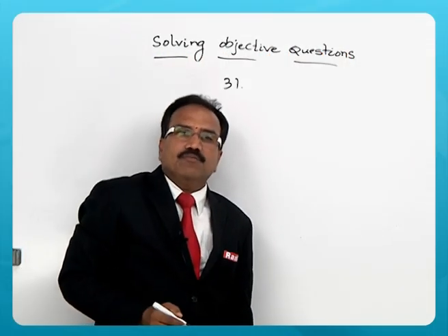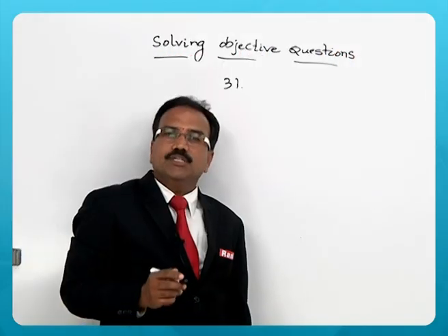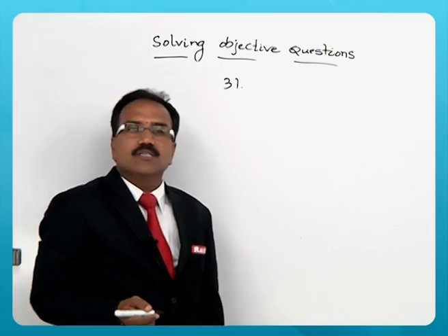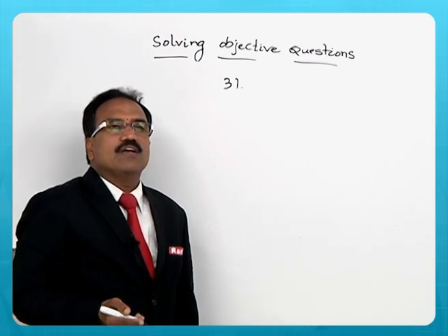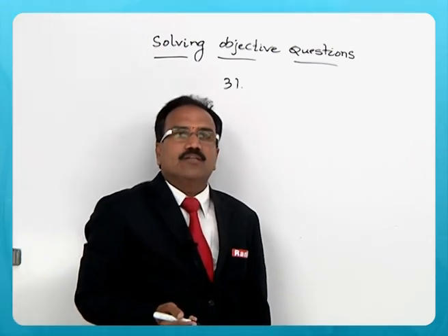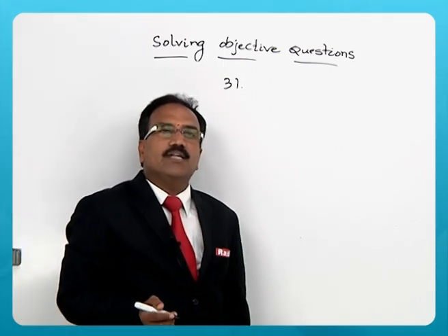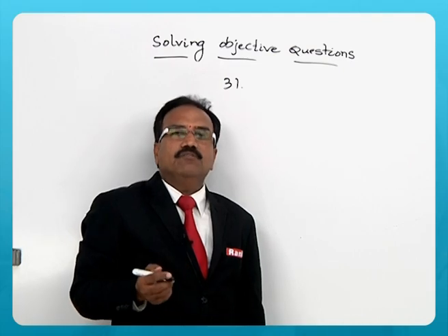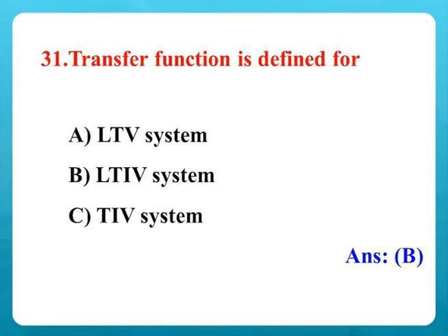Again, the transfer function is defined for question number 31 for which system? There is a limitation of transfer function because it cannot be applied to the time varying systems, non-linear systems, multiple input, multiple output system. So this transfer function concept, with certain assumptions, it is applied to linear time invariant systems. So among the options, option B is the right answer. Transfer function is applied to linear time invariant systems.